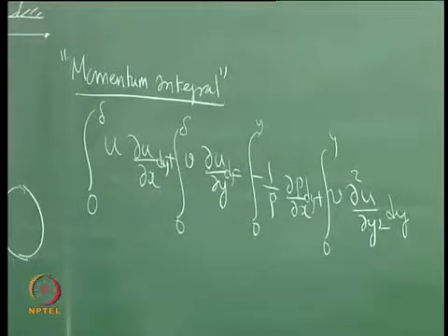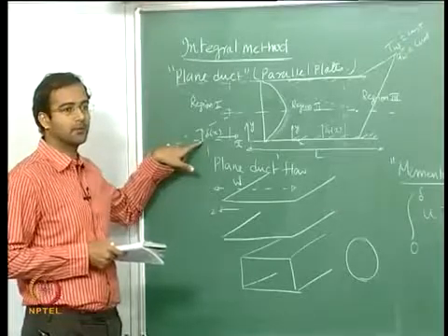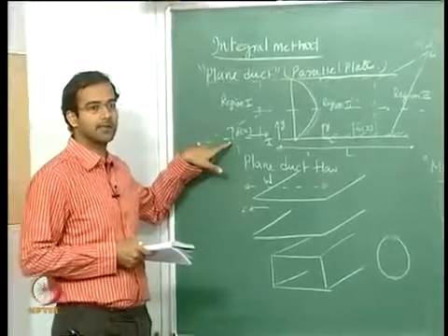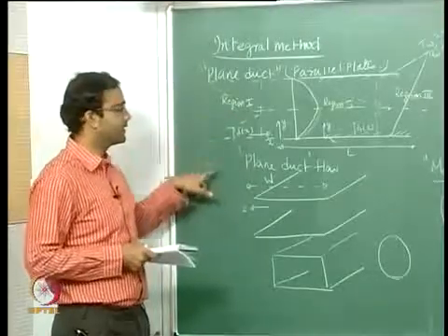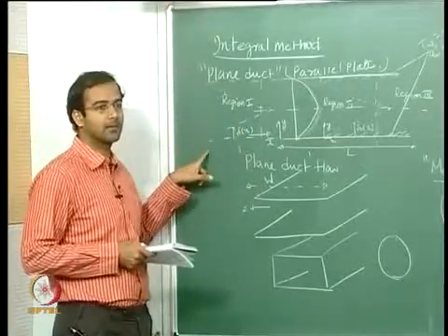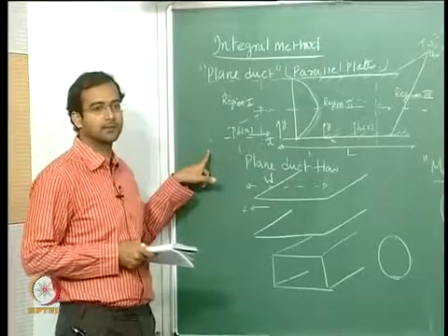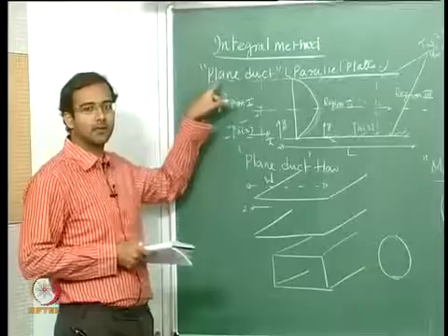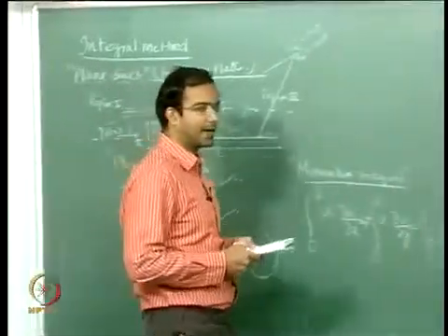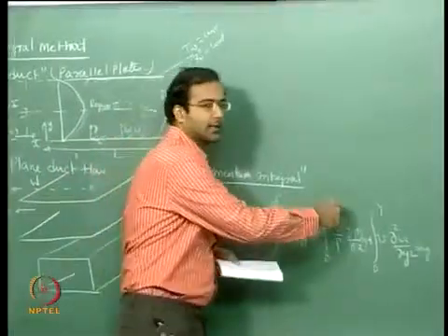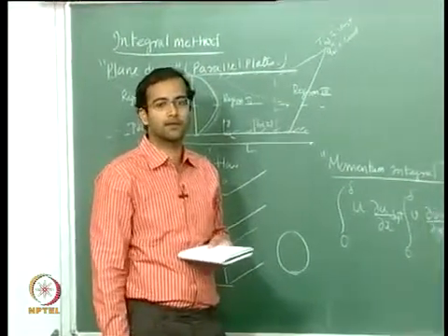Okay, so this can be applied for the momentum boundary layer when it is still in a developing state. Somewhere here you can find that the boundary layer thickness and the boundary layer variation looks somewhat similar to a flat plate case. So one plate here at the bottom, one plate at the top, but the additional problem that you have is this pressure gradient. So this makes it a little bit more complicated.